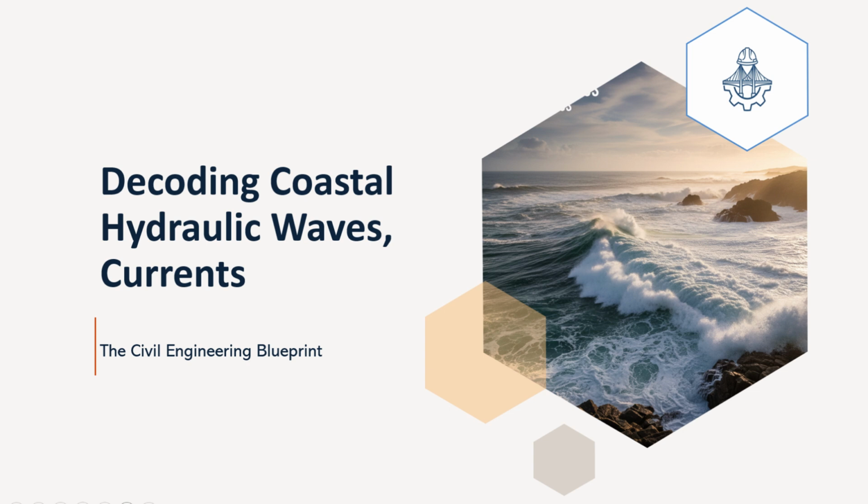Note, often alpha in deep water is the initial angle, and alpha is found using Snell's law iteratively. This comprehensive approach is what engineers must use for accurate nearshore wave height prediction. Let's run that second example calculation again, navigating complex depths using this combined approach. Remember, a slope with straight parallel depth contours transitions between 12 meters and 6 meters depth.